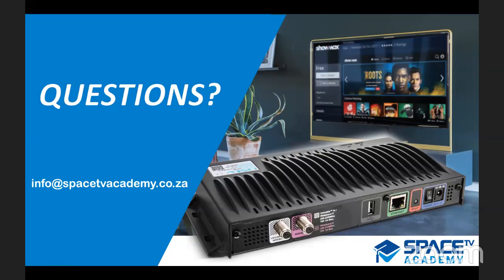Does SATIP not lose signal when it's raining? Joel, it will still lose signal because your loss is from your dish. It's on your downlink from the satellite to the dish. If there's a large enough storm, the rain creates noise, etc., and it does deteriorate your signal to your dish. But as I said earlier, hence the reason, use a commercial quality and a larger satellite dish that will minimize your rain fade. But you will never get away from rain fade completely. If it rains hard enough, they will even lose uplinks.